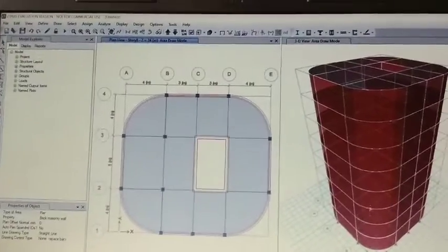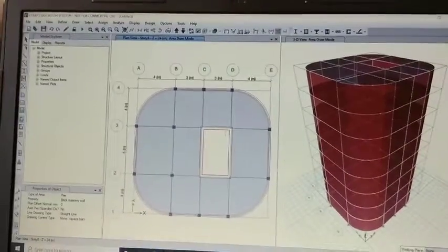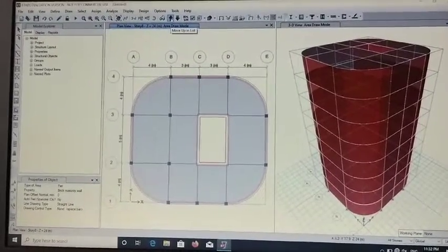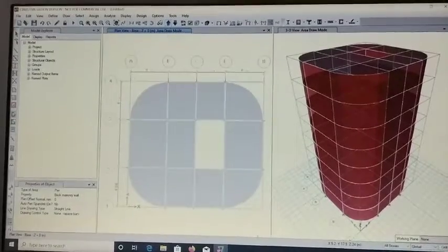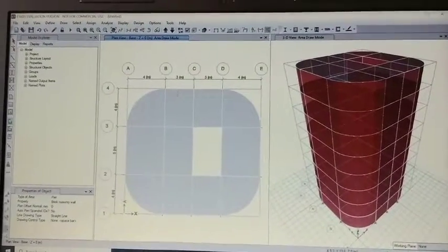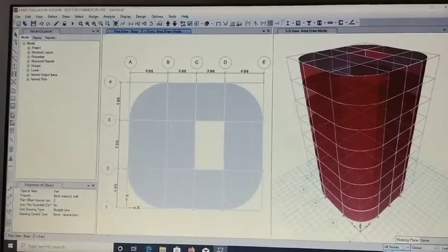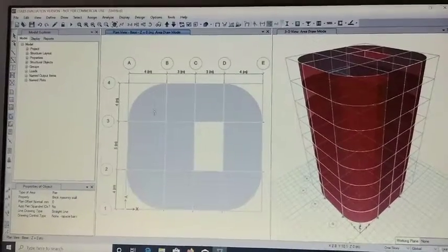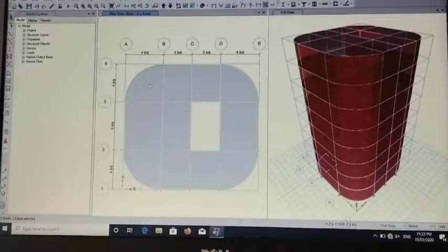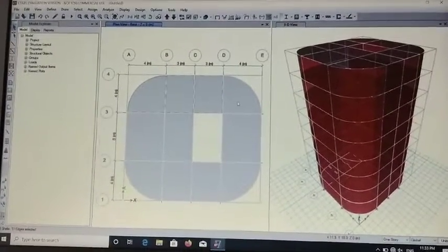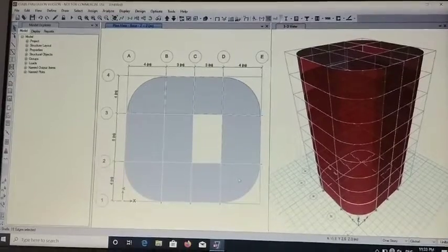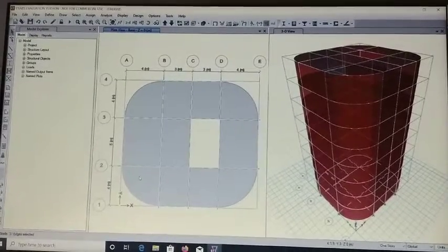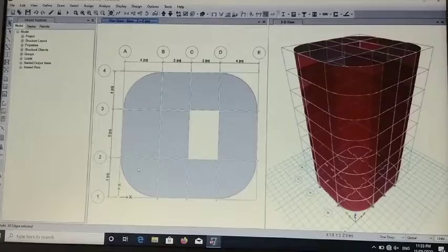For deleting the base slab, by using the arrow keys, go to base, select the one story option on the right side, select the base cells one by one. Press the delete key.